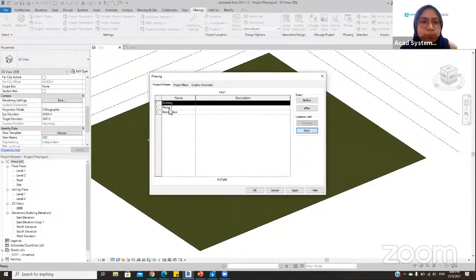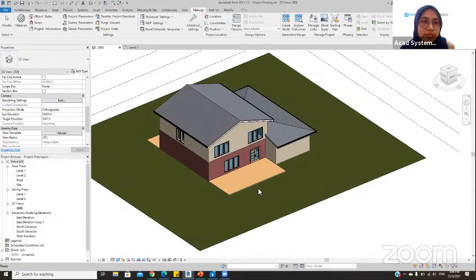All right. So from here, we can rename them. If you double click, you can just directly rename them. Let's say put here Demolish. And then I have here the Renovation work. Okay, so you can also put some description over here if you want to see them later inside the schedule, or if you want to refer to them later again. Okay, so let's go first to the model. Click on apply from here.